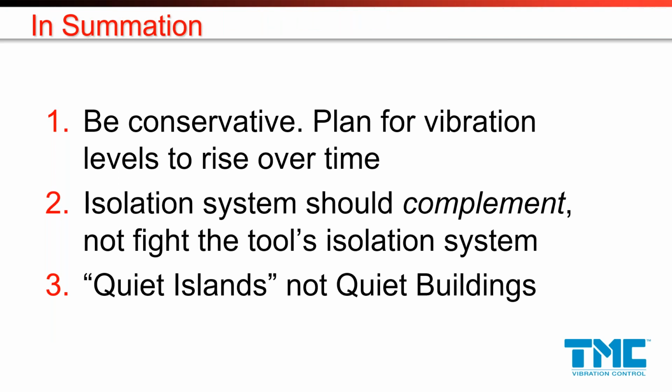So in summation, be conservative, plan for vibration levels to rise over time. The second is the isolation system always must complement, not fight the tool's internal vibration isolation system. So it's not necessarily the best vibration isolation system. It's the vibration isolation system that's the most compatible with the isolation system in the tool. And finally, to think in terms of quiet islands, not quiet buildings, for the reasons we've talked about.